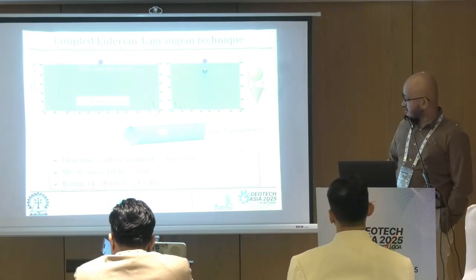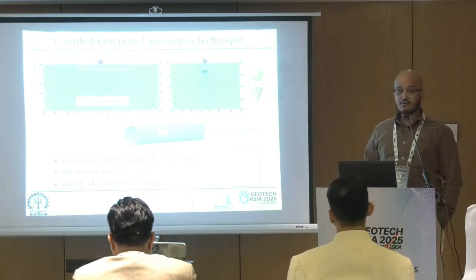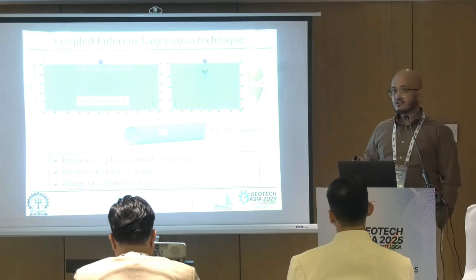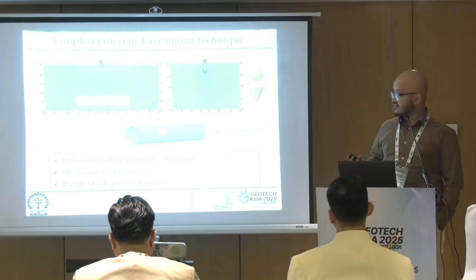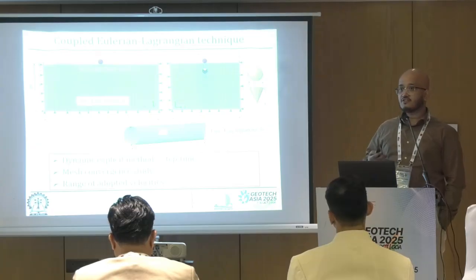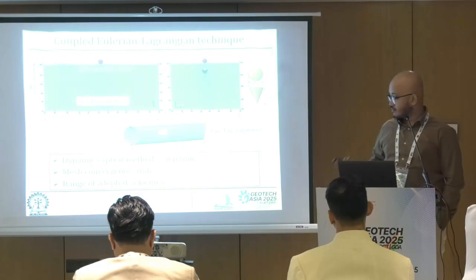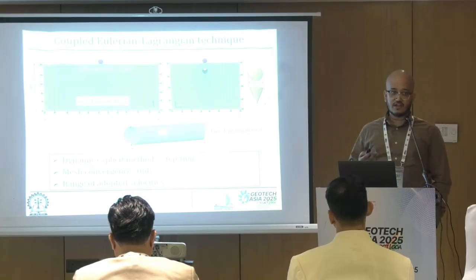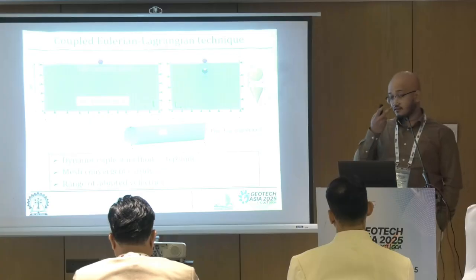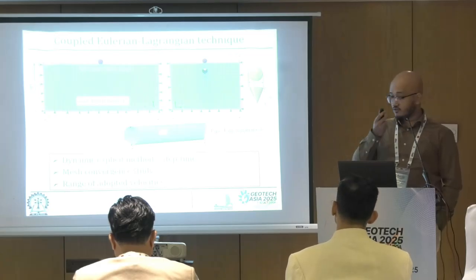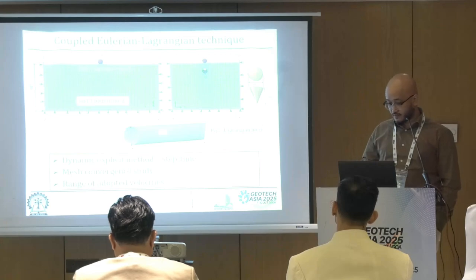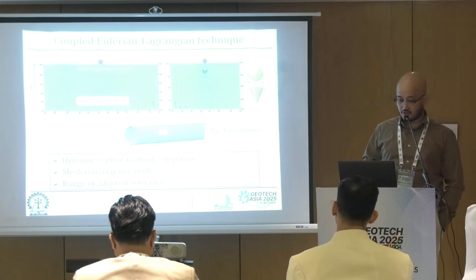Now, this generally is done using a dynamic explicit scheme. When we use such a scheme, it becomes very dependent on the time step that we choose, because it follows a direct integration process, and the step time eventually becomes a function of the mesh itself. So the mesh convergence study that we have to do is to ensure that the results are stable, in a sense that with a change of the mesh, we won't observe any significant difference in the deformation of the pipeline.